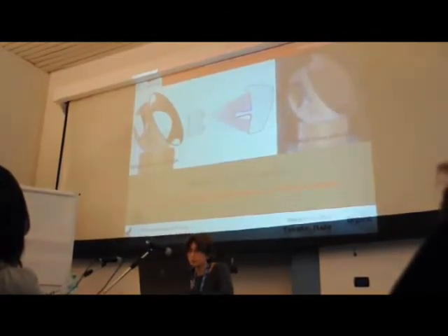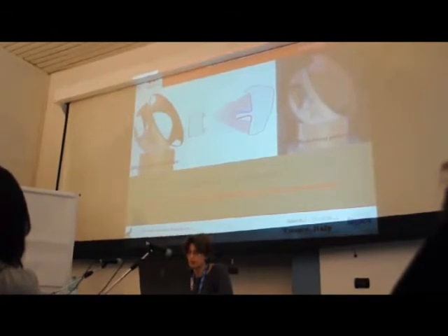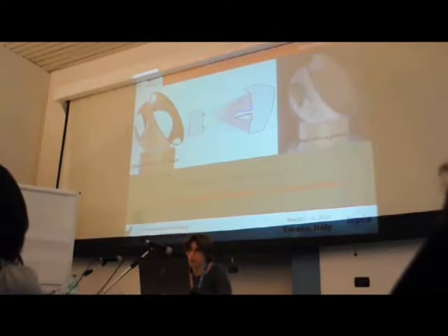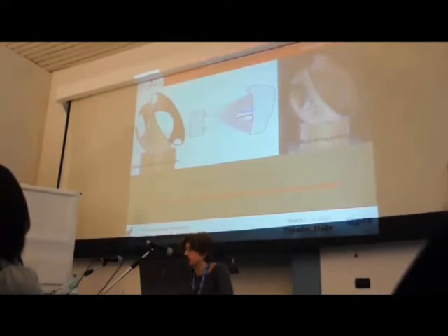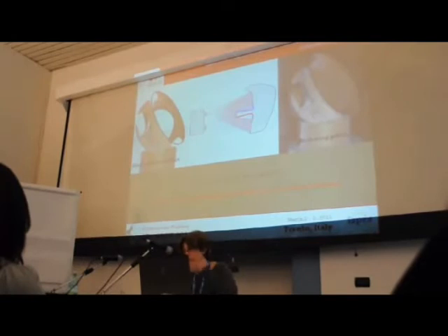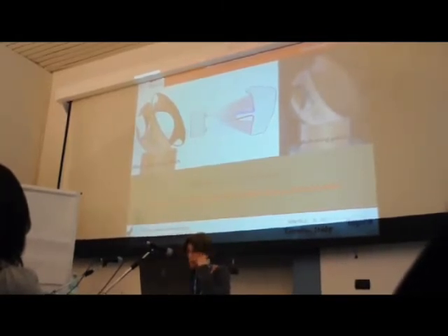Here I wanted just to underline that we need coincidental visibility for both emitter and receiver sensors. So for undercut views and hollowed regions, which shouldn't be arbitrarily reconstructed, wide mode is preferable because better results are obtained compared to macro mode.